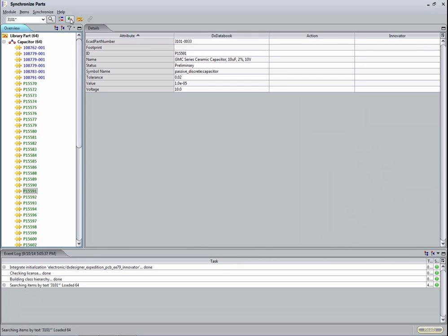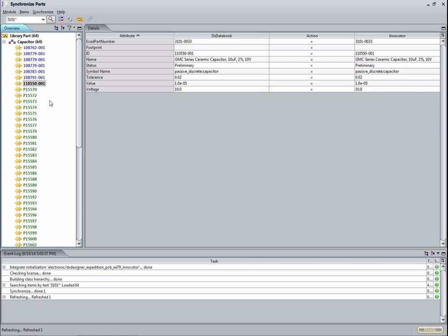If we start the synchronization, the selected component is created in our PLM system, and the defined metadata is also transferred. Vice versa, the created identification number is copied to the development library. It's possible to select several components at once and start the synchronization. Please be aware that the synchronization direction can be defined individually for each parameter within the configuration of Integrate. Also, component-specific parameters can be included in the synchronization.